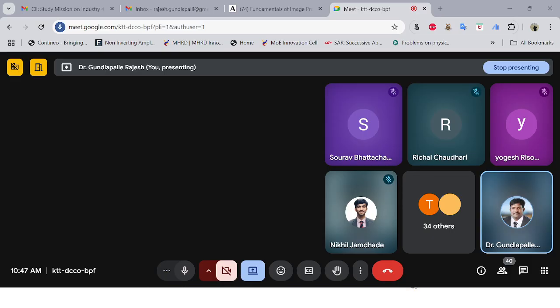Next, we have the multiply and accumulate instructions, which are combinational instructions, where two operations are performed using a single instruction. Suppose you want to do multiplication and accumulation, that is addition, with a single instruction, then we can make use of the MLA instruction, multiply accumulate. In the same fashion, multiply and subtract, we have MLS. Then to multiply 32-bit numbers, we have MUL. Then SDIV, signed divide, then signed multiply and accumulate.